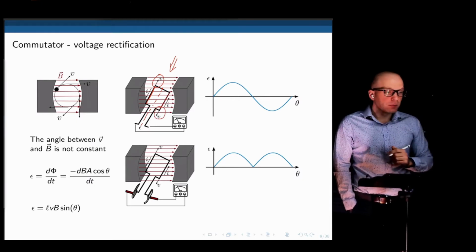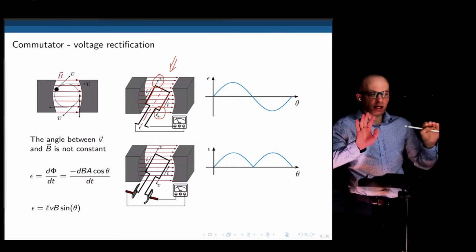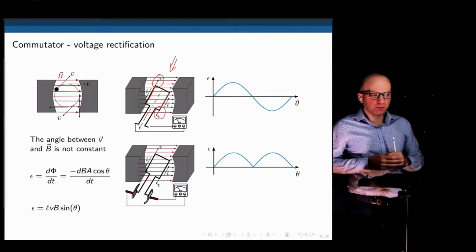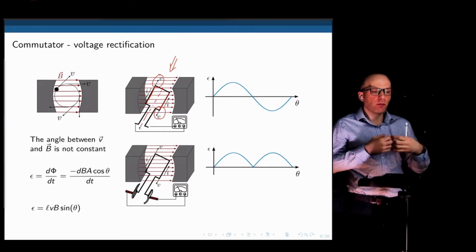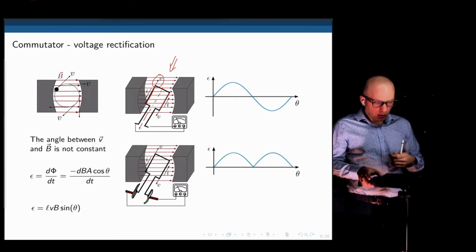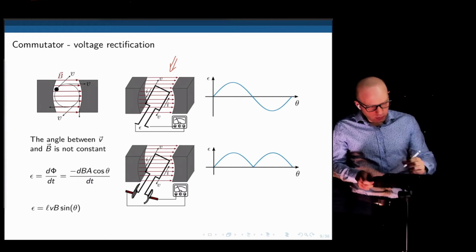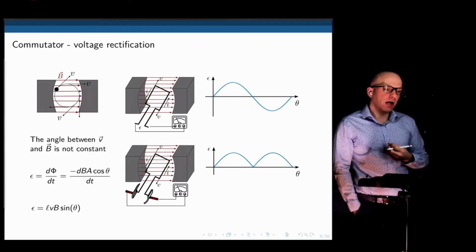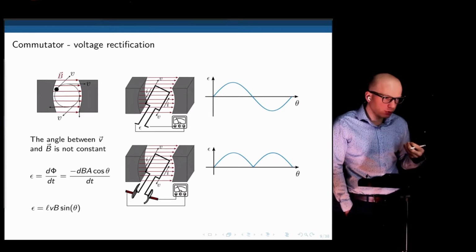Now you see that both sides of that coil are rotating in opposite directions with respect to the magnetic field. So the current that they generate, if you create a closed path, will be in opposite directions. Because we need a changing magnetic field, we can make an approximation and count the number of magnetic flux lines that the wire crosses to determine the strength of the EMF it produces.